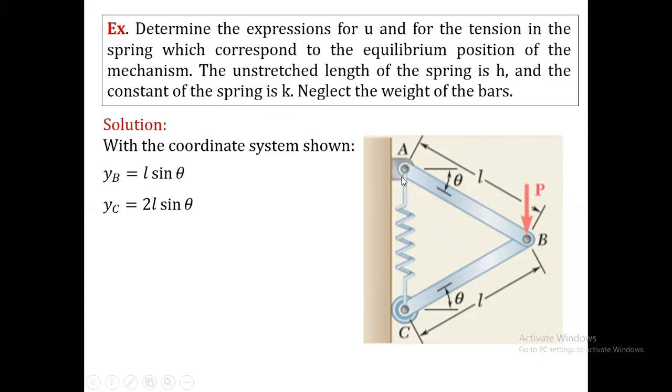It is visible from the supports that it is supported at points A and C. But at C it is roller supported. That means restriction is provided in the x-axis, no restriction in the y-axis, that is, no restriction in the vertical direction. But at A it is hinge supported. That is, it can rotate, but it cannot translate in the horizontal or vertical direction.